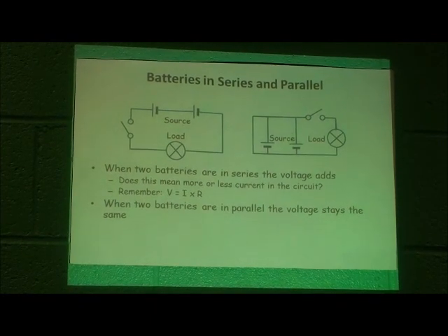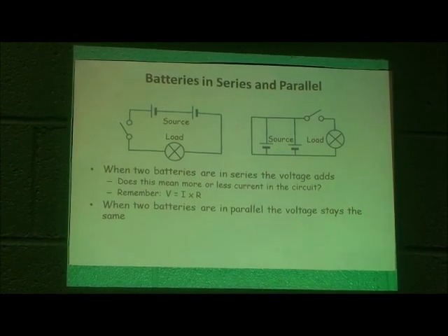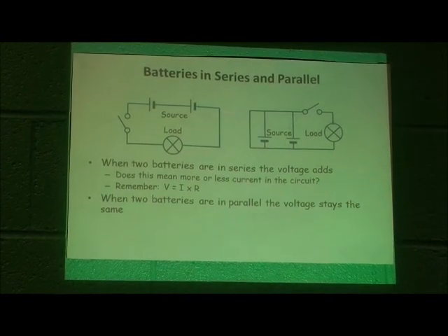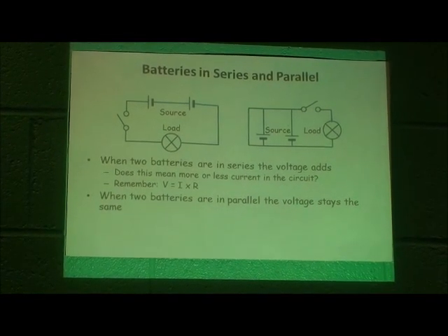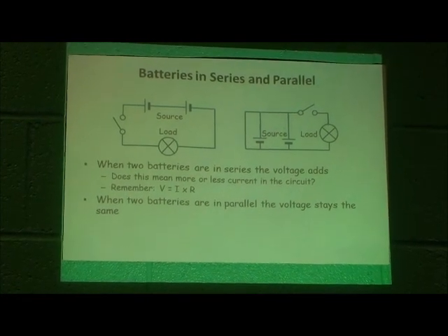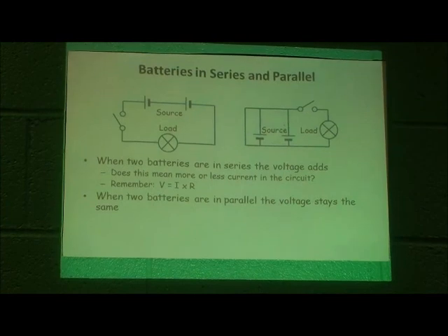When two batteries are in parallel, the voltage stays the same. One thing they should be aware of is if you're going to put them in parallel, you need the two batteries to be the same voltage. Don't try to put a 9-volt battery in parallel with a 1.5-volt battery, or you're going to cause some problems.